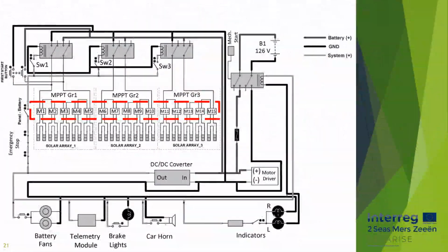There is also interesting research, like using boost-type micro-MPPTs on solar cars. In this electrical schema, there are three parallel MPPT groups. Each MPPT group has 5 serially connected MPPTs, and each MPPT is connected to 2 serially connected PV modules. The idea is to decrease the loss from partial shading and prevent the loss of a whole PV region. MPPTs on solar cars are designed considering the fast-changing energy needs and weather conditions throughout the whole challenge. Their efficiencies are higher than 99%.